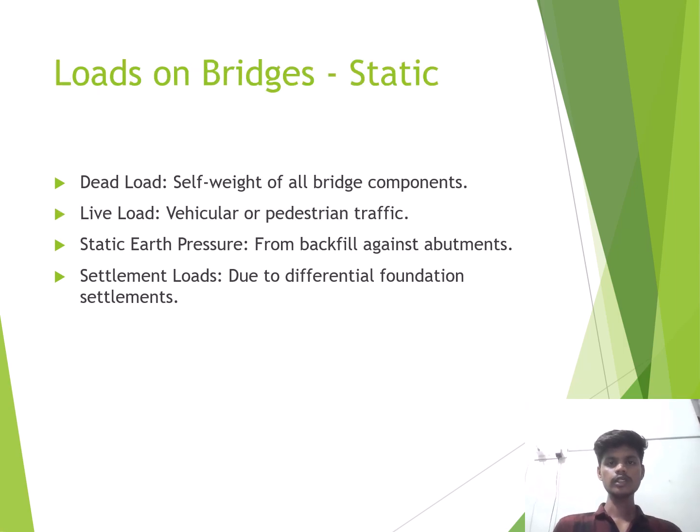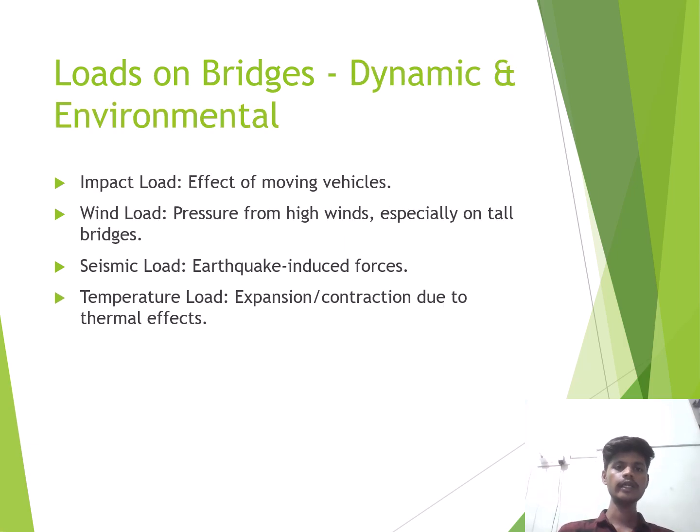Loads on bridges. There are two types of load: static load and dynamic load. First one is static load. Static loads include various loads like dead load, live load, static pressure, and settlement load. And in dynamic or environmental load: impact load, the effect of moving vehicles.